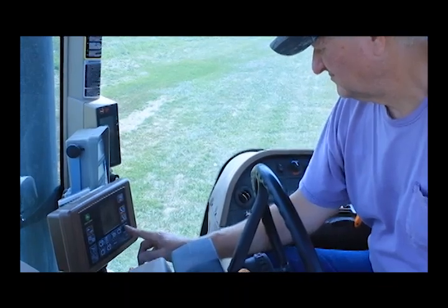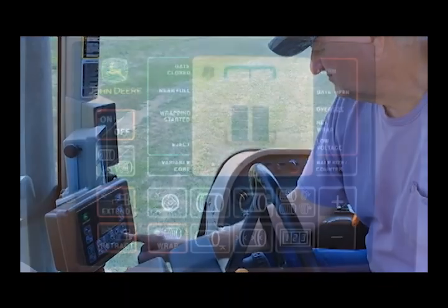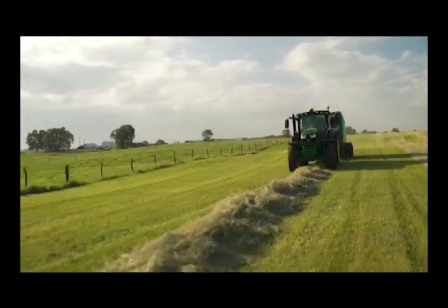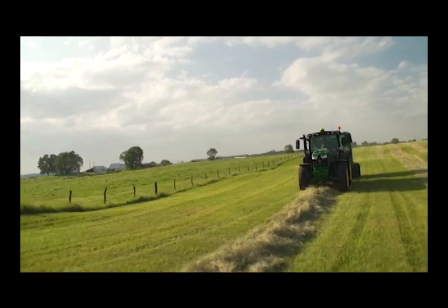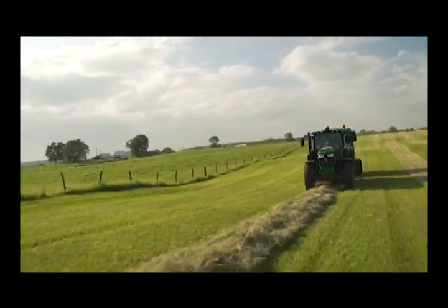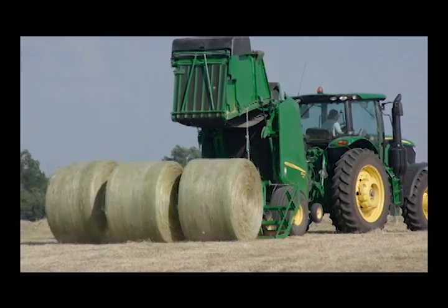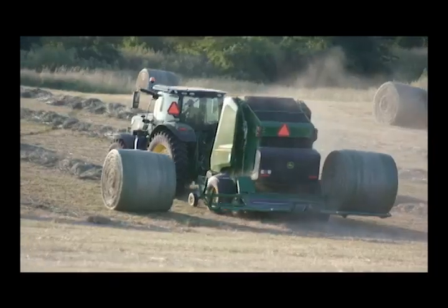Even though you can adjust these settings immediately, it is recommended to run your baler with the factory settings for the first 50 bales. This break-in period will increase baler life and reduce maintenance. Also, this period will help familiarize you with the monitor and the baler operation before adjustments are made. During this break-in period, a smaller and lower density bale is recommended.